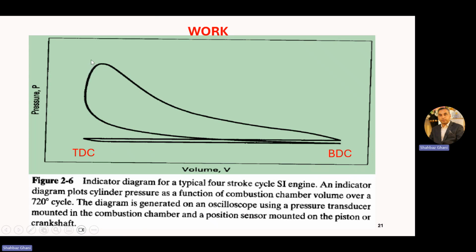Combustion took place. Now the piston is in the power stroke. From this TDC, it is going back to BDC. The volume is increasing, the pressure is dropping, and here your power stroke or the expansion stroke finishes at BDC. Volume increased, pressure decreased, you get the power.